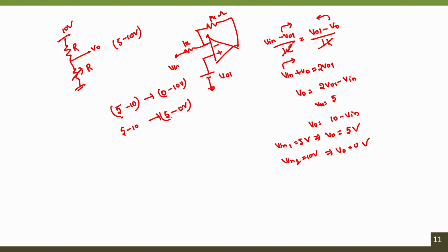If this is okay, we can simply use VO1 as 5 volts, but with this reversed order, again in the next stage we may have to compensate for this reverse order, else the results would completely change, or even in the microcontroller programming we have to compensate for this reverse order swapping.